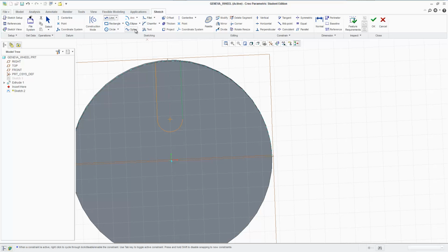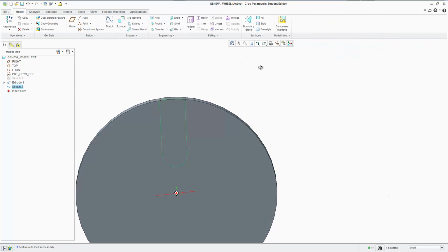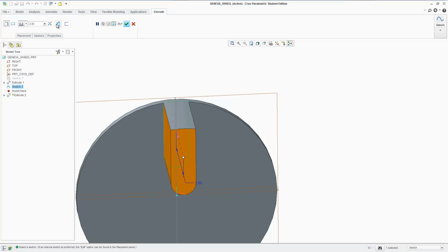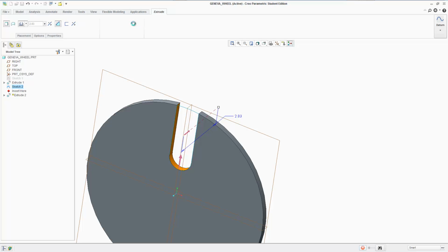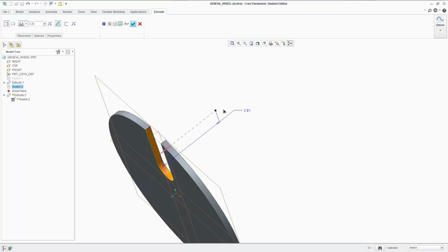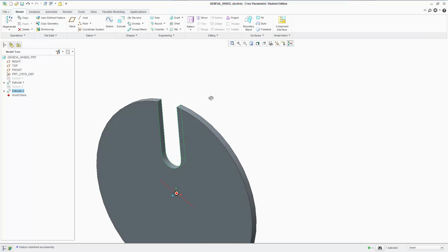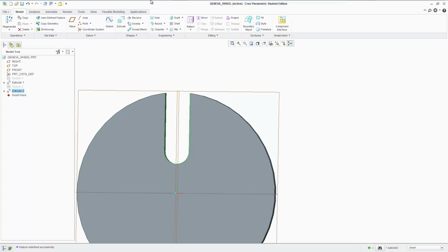And now we're going to make an arc again. Hopefully we do it right this time. Okay, that's that. We're going to extrude out to the other side. There we go. It's doing it right now. Actually, let me go back to the extrude. See how it's extruding outwards? I don't know if I went over this already, but I'll go over it again. Right here, click and drag, and select the one that says up until the next surface. I think I already went over the double-sided one as well, and there's a bunch more, but that's what we need right now. So we have our slot.